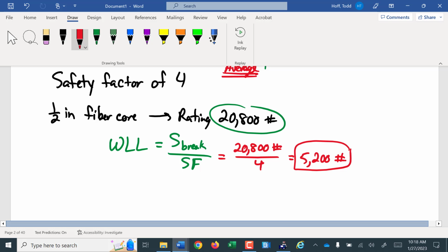Well, the same thing here. The safety margins usually account for that construction load, but they pushed it a little too close for one. Had that been a healthy bridge, it would have held. But the other reason for the safety factor is because over time the bridge weakens. Bolts might get loose, pieces rust and get thinner. None of the metal under that bridge is the same thickness it was when it was new. It's corroded. Stress over time causes stress fractures or cracks in that metal. So all those things are accounted for in the safety factors.